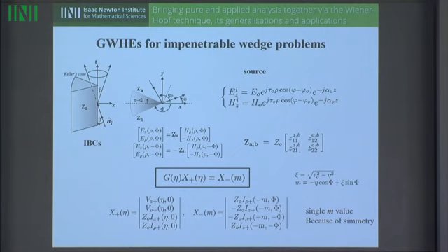The wedge: we take the angular regions on top and the bottom to be of the same size, phi, and in this case it means that the m related to the upper region and the lower region are the same. In this case, we apply surface impedance boundary conditions in a general way with anisotropic impedances, and we get from the equations shown before this system of equations.